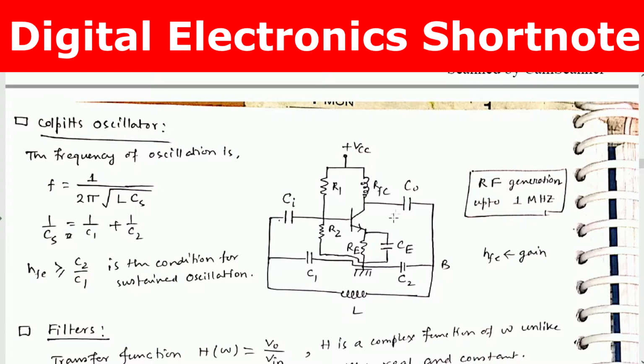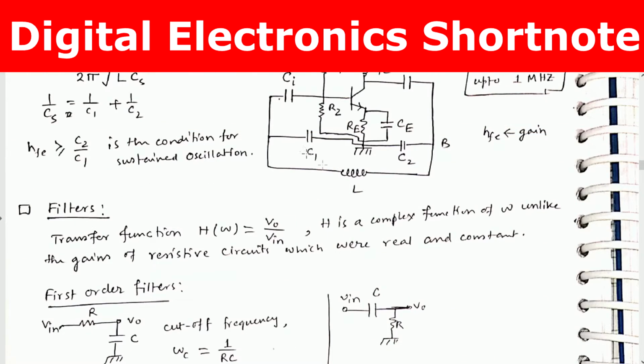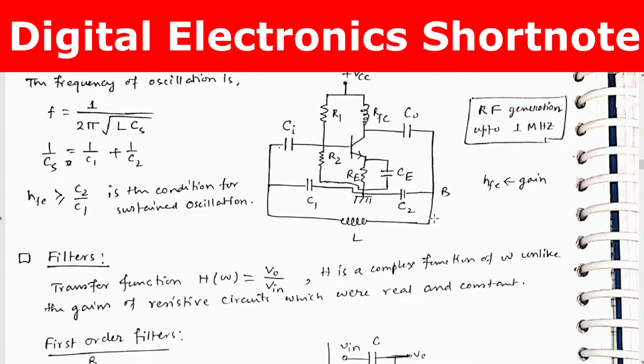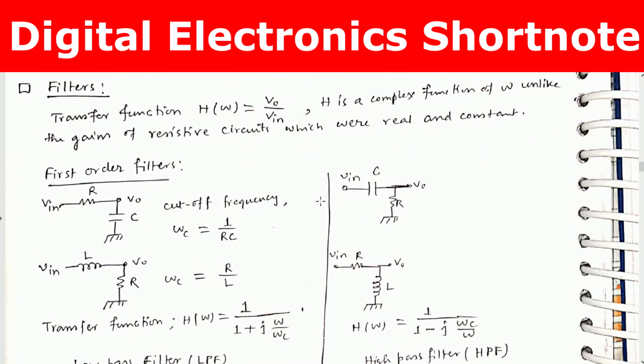Let's talk about Colpitts oscillator. This is Colpitts oscillator. The difference is that here in Hartley the inductors L1, L2 were there, but here the same thing, with capacitors C1, C2, and L will be here replacing C. So this produces RF radio frequency up to 1 megahertz. hfe is the gain. hfe greater than or equal to C2 by C1 is the condition for sustained oscillation, and the frequency of oscillation is 1 by 2 pi root over L into Cs, where 1 by Cs equals 1 by C1 plus 1 by C2.